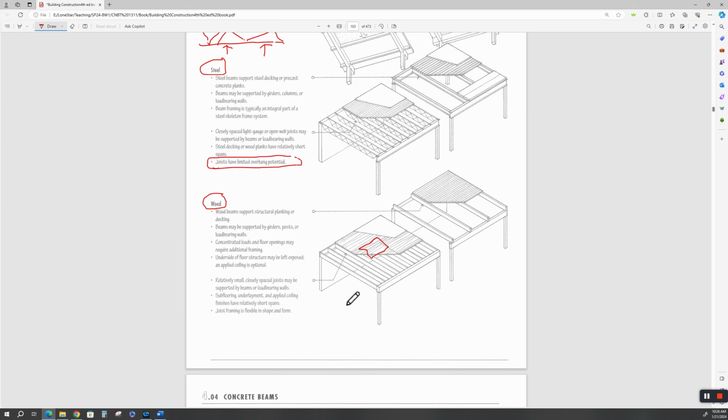All you've got to do is support the weight of the construction loads up here, and you might have to put jacks underneath there and jack beams while you're laying the deck down, gluing it and screwing it, or using ring shank nails to create this diaphragm until the glue cures, and then you can remove the jacks underneath it, and it'll support more of a load.